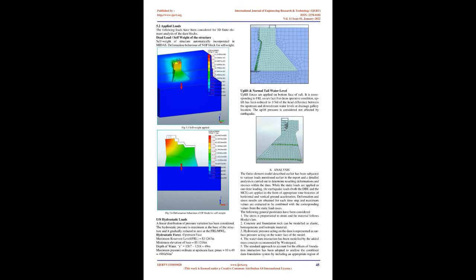Finite element time history analysis consumes a lot of computer memory and requires more analysis time than static analysis. Hence, a reduced number of elements in the model is used without compromising stress values and distribution pattern. The various views of the model have been shown below.